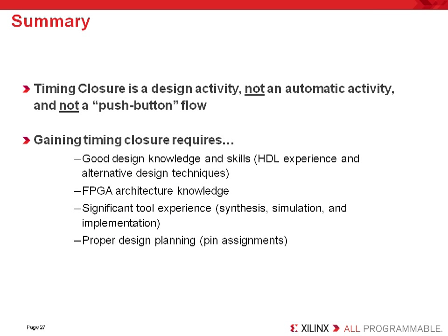In summary, timing closure is a design activity, not an automatic activity, and not a push-button flow. Gaining timing closure requires good design knowledge as well as good HDL skills. Good FPGA architecture knowledge is also a requirement. Significant tool experience is, of course, essential, and proper design planning, especially with pin assignments early on, is very important.